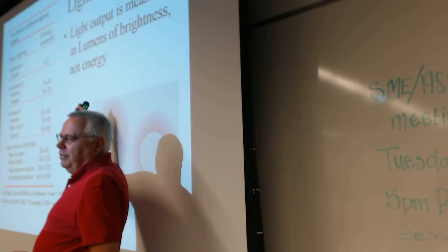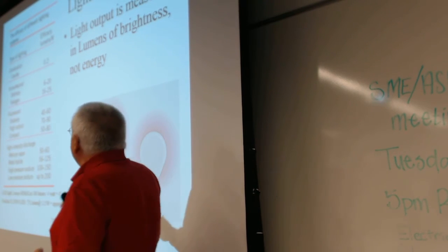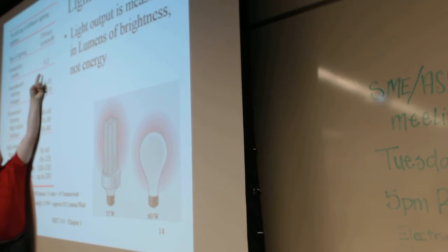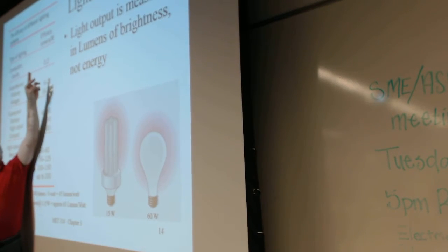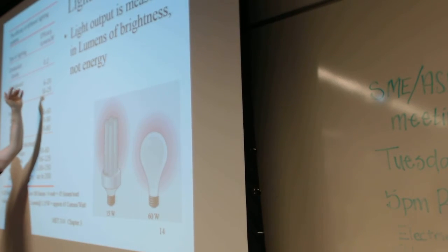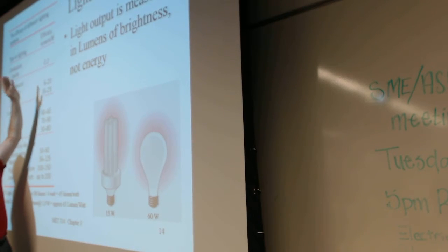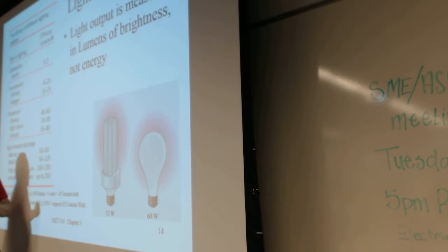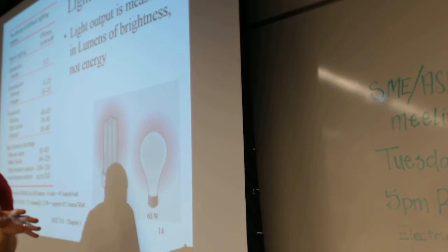We'll all be talking about efficiency here, but just to scale things, what is the output? Lumens. What is the input? Watts. Because they aren't the same unit, it's not efficiency. But how effective is it? What is the efficacy? Effectiveness works for me too on this, but lumens is not a power output so much. It's how much light is there. A 60-watt light bulb doesn't put out watts.